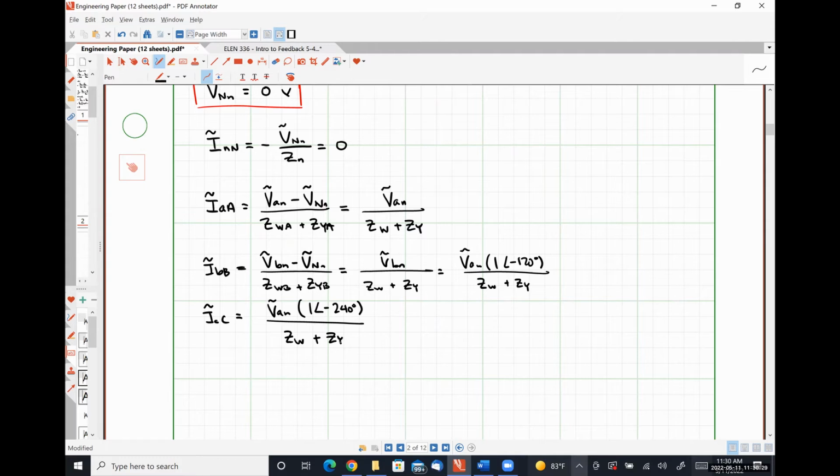However, the blower, a smaller induction motor that's used to force air in or out of the system, is typically a single phase load, so that we inherently have an unbalanced load per building, right?